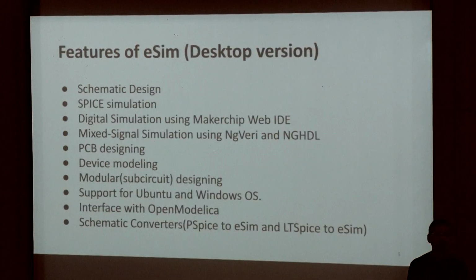So moving on to the next slide. Features of eSim: the first one is schematic design, then SPICE simulation, digital simulation using the Makerchip web IDE, then mixed signal simulation. Mixed signal simulation is a niche area and it's very useful. It is achieved using NGHDL, integrating SPICE with Verilator and GHDL.